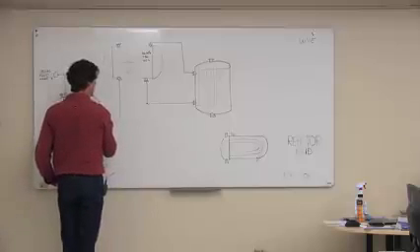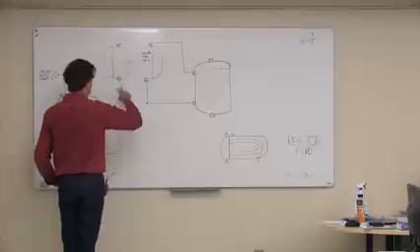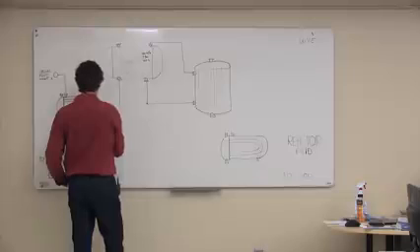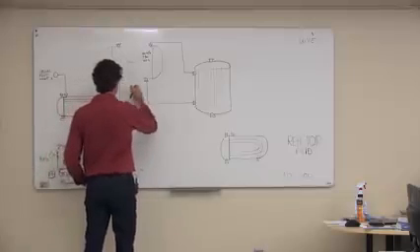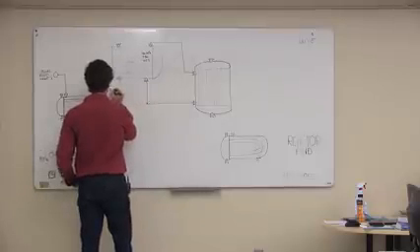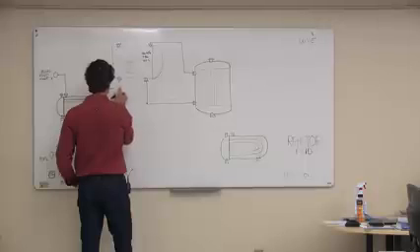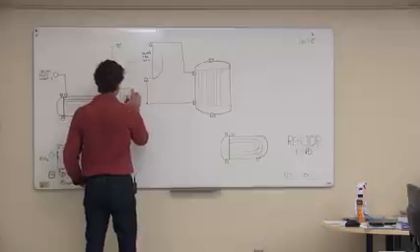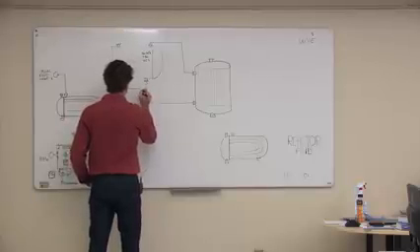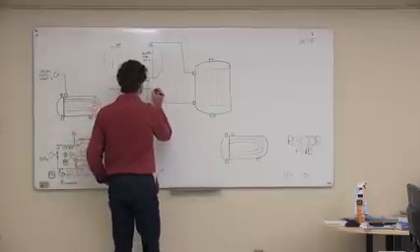We're going to come out here, and we got to get into that reactor there. So we got to weave our way around here a little bit. I think I'm going to cut it across here. And okay, so horizontal lines break vertical lines when they're major process lines. You could argue that this syngas is more important than the utility water, in which case it should break it no matter what direction it is.